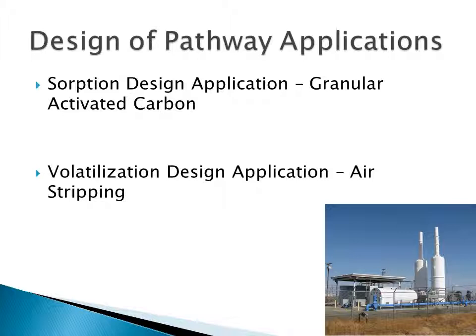The internal components of an air stripper are selected to ensure that mass transfer takes place under effective and economical conditions. The packed material is one of the most important factors in stripper design. The packing material provides surface area for the air and water to interact and creates turbulence in the water stream to expose waste surfaces to the air.